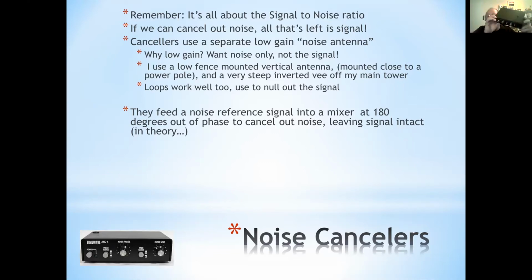And all of these boxes, by the way, have transmit receive switches built into them. So if you have a 100-watt radio, you can actually put these in line with the radio, between the radio and the antenna. And as soon as you key up the transmitter, it'll automatically bypass it so you won't damage it. If you've got a radio like my FT2000 that I use, it's got an external receive input port, and I run it through there, so I don't have to worry about the TR switching, because I'm using this on a receive antenna. But basically all these things are pretty common. They have the same three little ports on them.